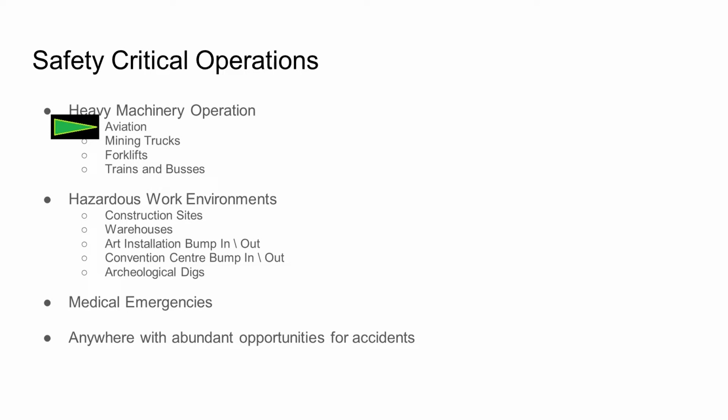So if you're coming in for a flaps down landing, you've got to make sure that before you deploy your flaps, you're not flying too fast, because if you deploy your flaps while flying too fast, they might come off, and that's not good. But you've got to make sure you don't wash out too much of that speed, because if you go too slow, you might go below the stall speed, and then your aeroplane will just drop out of the air because you don't have any lift anymore. So it's a stressful situation.